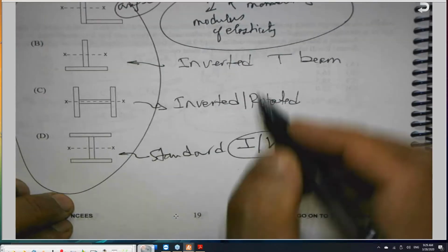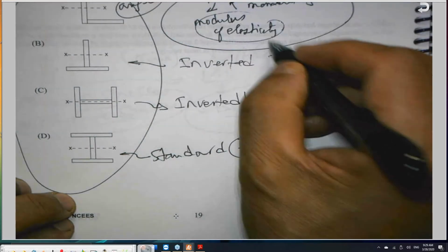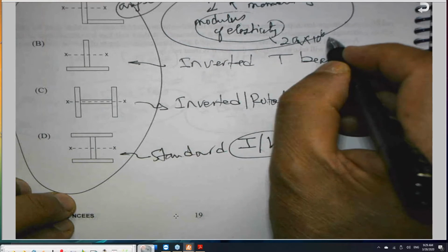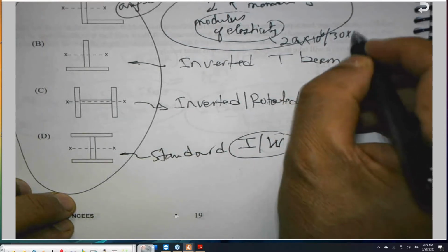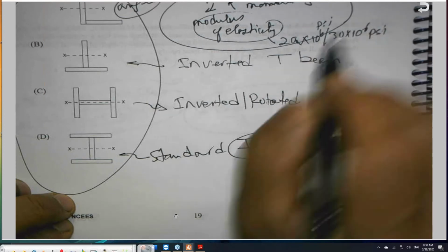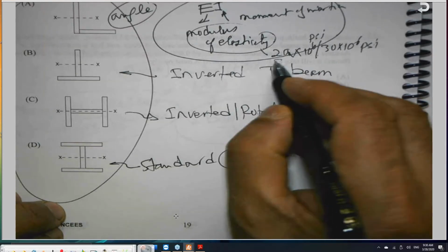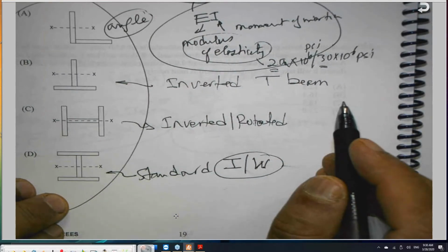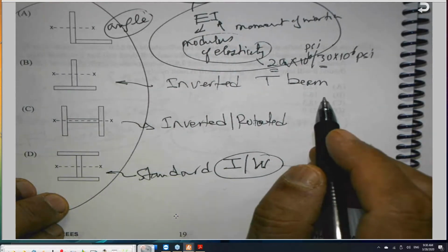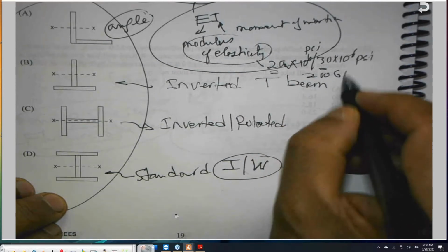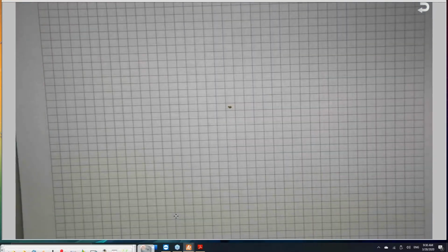And the modulus of elasticity of steel, as you know, is one number, which is 29 million psi. Some books use 30 million psi. I have no problem with that. 29 is the standard number for E for steel, based on the steel manual, or 200 gigapascal, 200 GPa. So all this we need to be ready for.